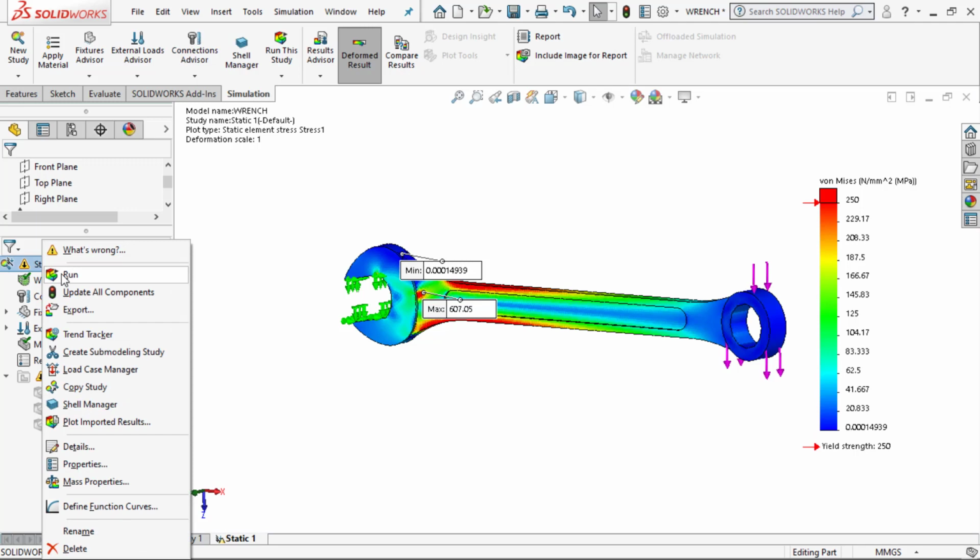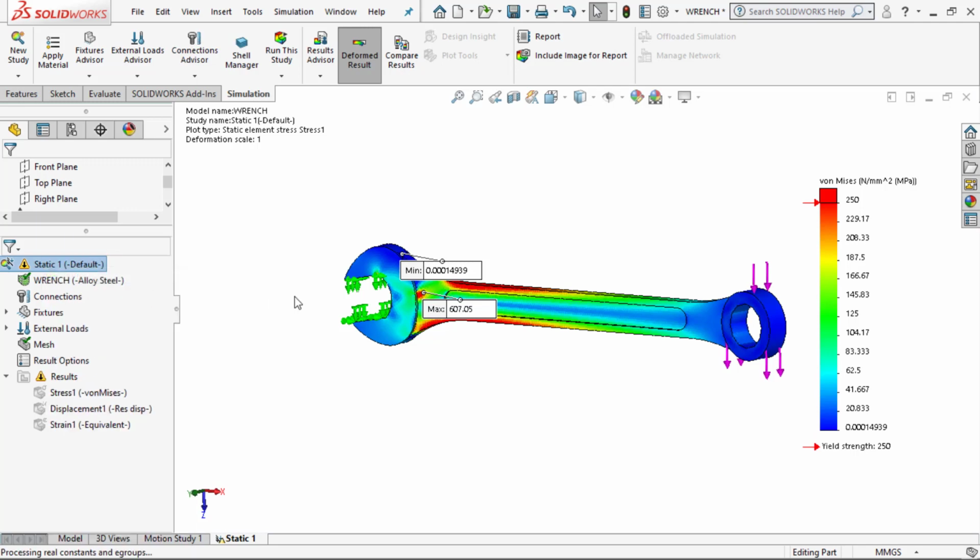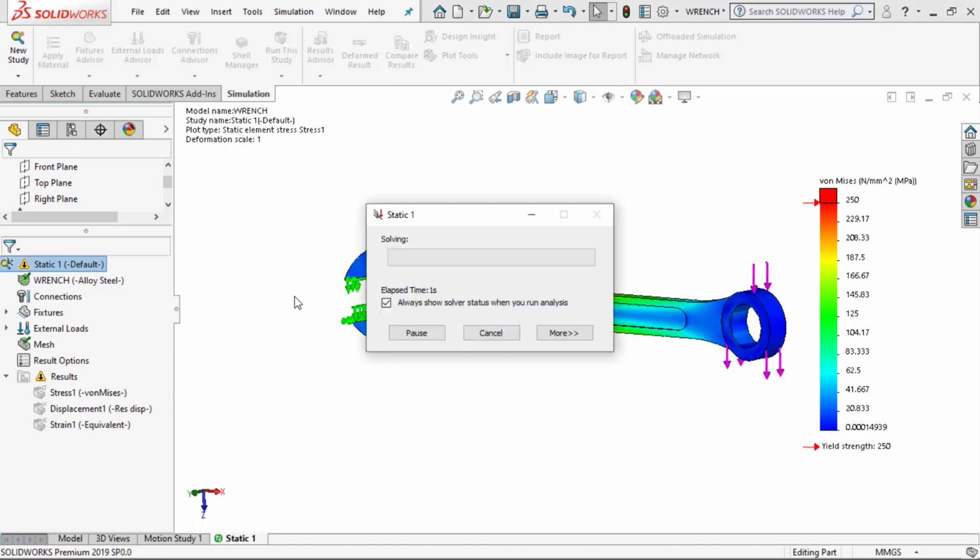So we had seen the maximum stress is 607, right? Remember, stress is independent of material selection. Okay, and the displacement is dependent on the material, because with respect to aluminum, brass, steel, the displacement will be different. Okay, so the Poisson's ratio will also be different, right?